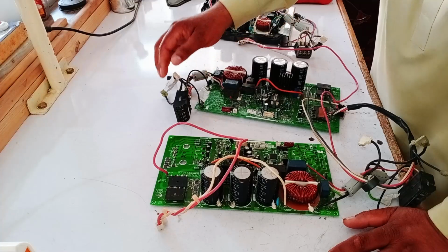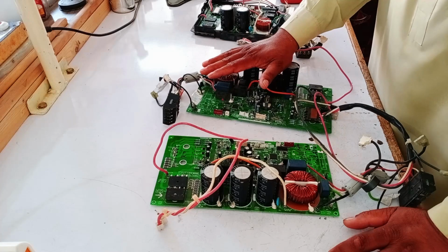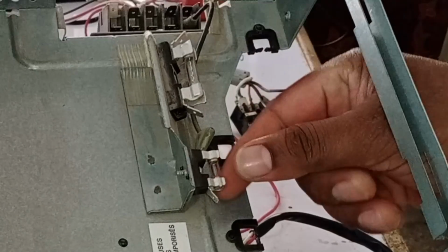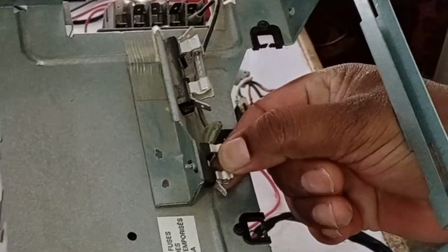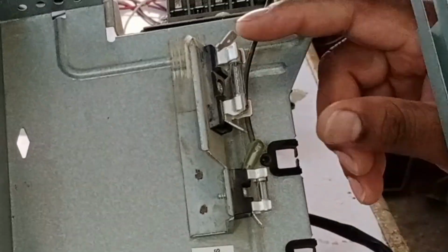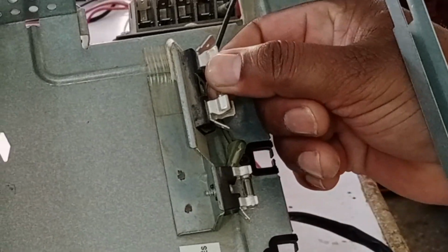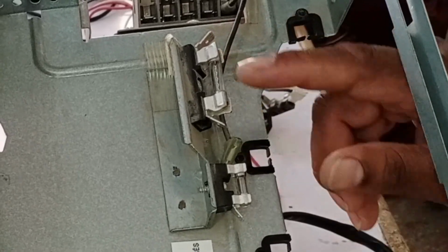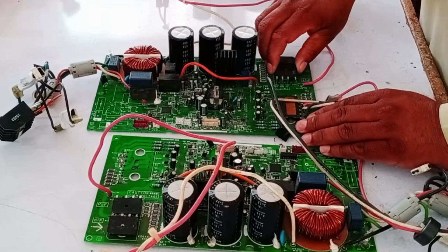Now, let me tell you that when you are checking a 1.5-ton or 2-ton unit, you will see that there are 2 fuses inside. If these fuses develop a loose connection within their holders, they can cause sparking. That's why it is very important to check them properly to ensure that no fluctuations occur due to this issue. If these fuses are faulty, replace them, and your fault should be resolved. The next step is to check the rectifiers.